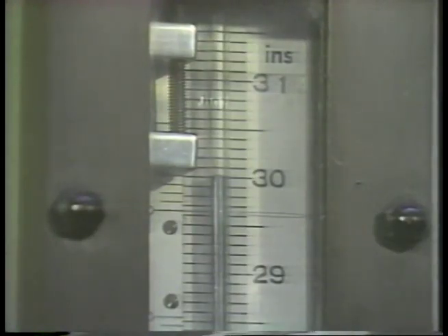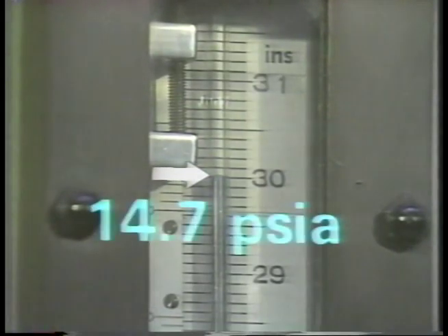We said that the flow of mercury out of the tube stops when the atmospheric pressure and the pressure exerted by the mercury in the tube are the same. In our example, both pressures were 14.7 psi. This is another example of balanced forces. Now, if the mercury level in the barometer holds steady at 30 inches, we can conclude that atmospheric pressure must be 14.7 psi.